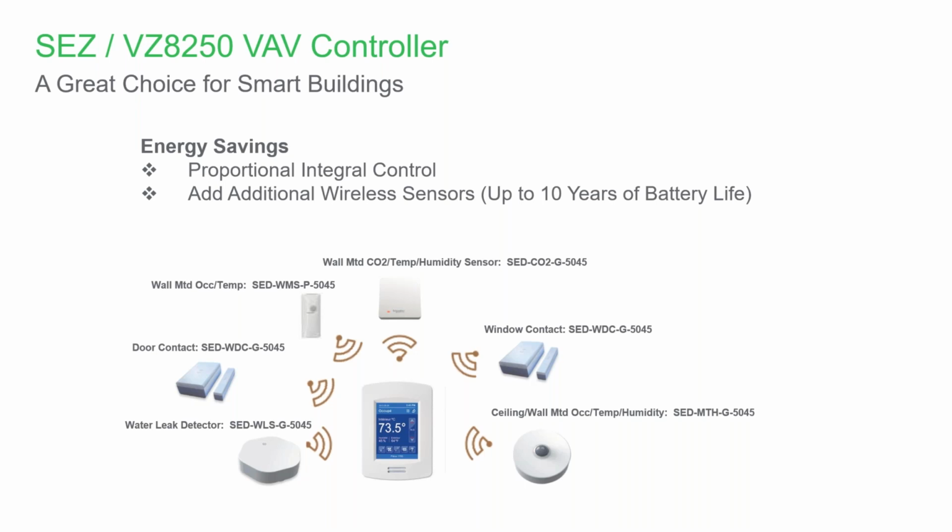But with the addition of door contacts, we also have a feature that looks at that PIR and it looks at the door. And probably the best way to think of this is if you put yourself in the mindset of being in a hotel room. You're the only person in there, and you go out the door with a door contact on it. Obviously, there's nobody in the room, so there's no motion, and the door has been opened and closed, so that's what we refer to as a cycle. If that happens, and you've enabled that feature inside of this room controller, it will automatically go into unoccupied mode,